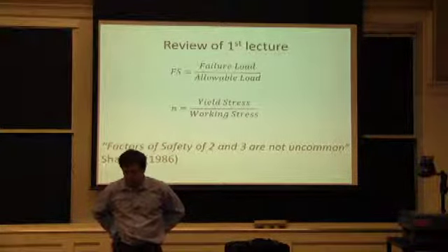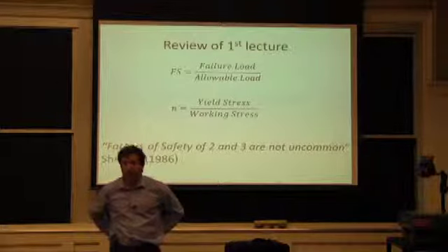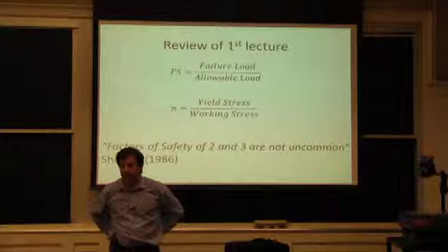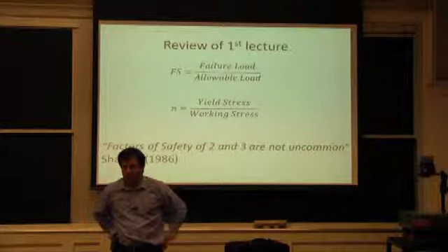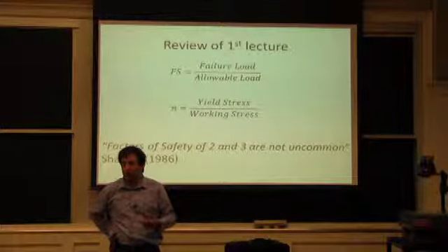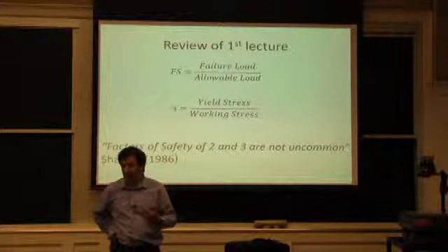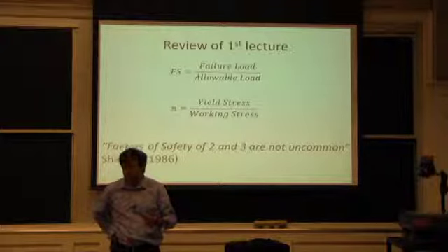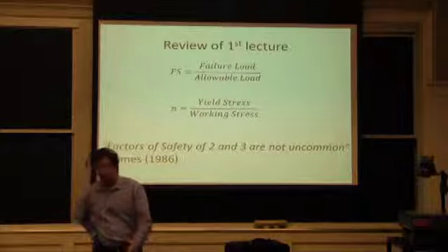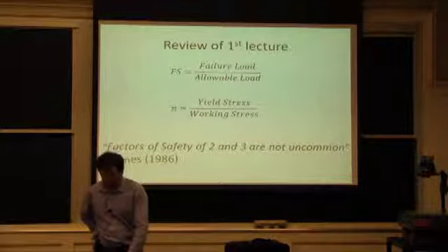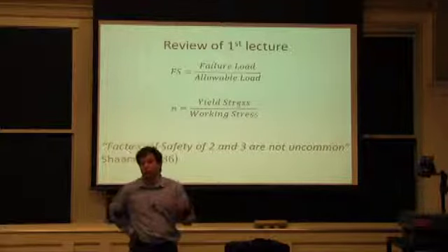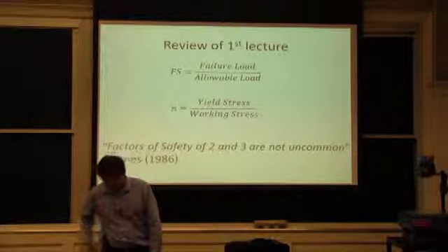Although when we were talking about the ASME last week, it has a very high safety factor, but it's based on the mean value of the pressure as opposed to including pressure variation from closing valves, from water hammers, or everything you can have. So we could probably argue that ASME works with the second definition, where even by design you know that you will exceed your working stress sometimes.